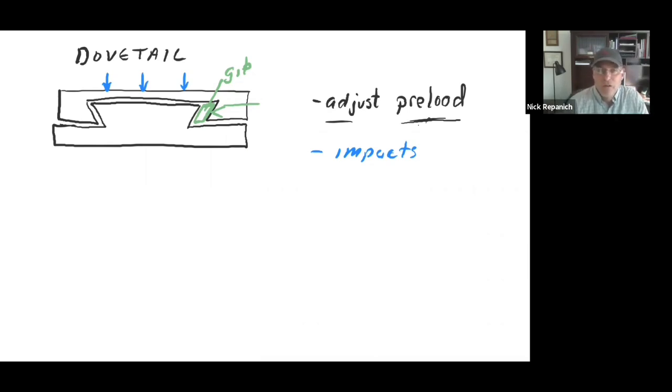I always thought about aluminum heads on your engine. You got a steel block and an aluminum head. How do you deal with the gasket material that'll handle the expansion on the aluminum right in the hot spot? It's difficult. And if you can make it work, great. And eventually it doesn't work and you blow your head gasket. There's some engines, like the Toyota V6, where it's so predictable. You hit 80,000 miles and your head gasket blows, because it's expanded, contracted, and that's the life of it. And every time it did that, your tolerances changed.